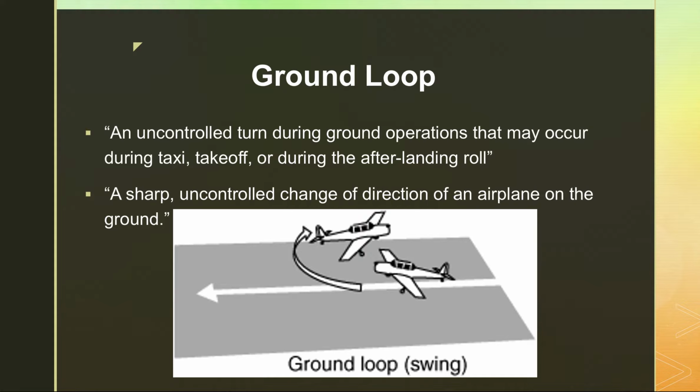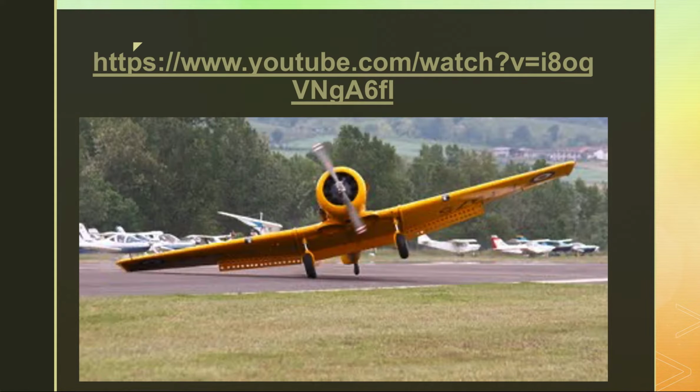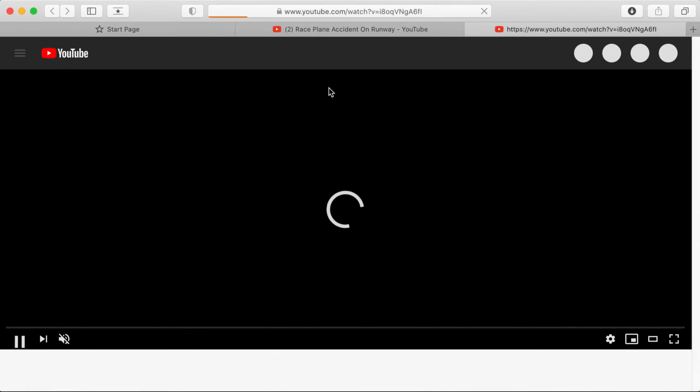And because this picture doesn't do us all that much justice, let's see what a ground loop looks like. More common with tailwheel aircraft, it doesn't mean that you're always going to drag a wingtip, it just usually happens that way. It's pretty hard on the landing gear, it'll pop tires off beads, and a lot of times the aircraft will nose over and hit the propeller into the ground and cause some other maintenance to need to be performed.